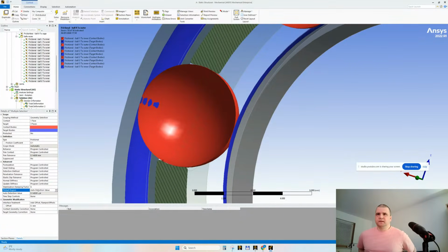Where I was pointing is here, it can be kind of forgiving in static and transient. If you do some things wrong or the topology is not correct, maybe you can somehow adjust it with these settings and values, but not in explicit dynamics.